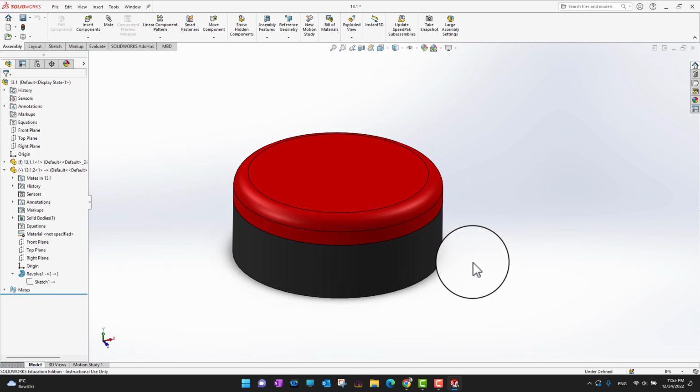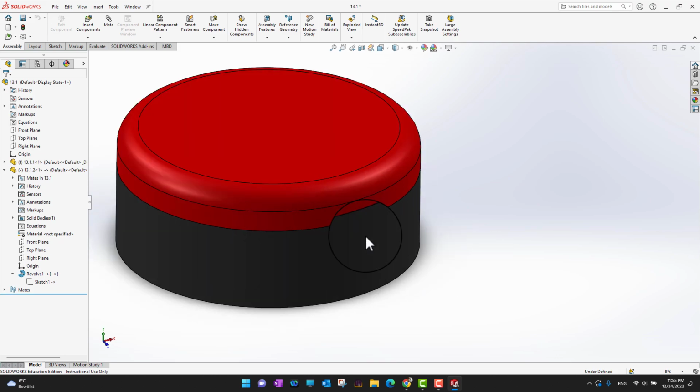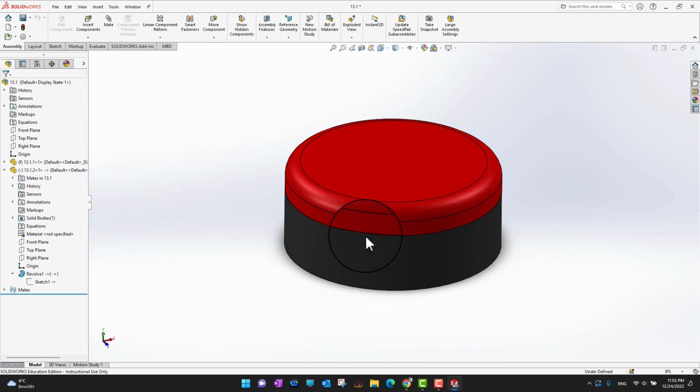Whatever modification you want to make in the base, the reference is going to follow that. In this way we can control one sketch on the basis of another sketch. This is in context modeling. What you need to do is edit a part in the assembly environment. No matter which dimension of the base you want to change or modify, you just need to create a relation between dimensions or any outer or inner surfaces wherever you want. In this way you can control one part by using another part.